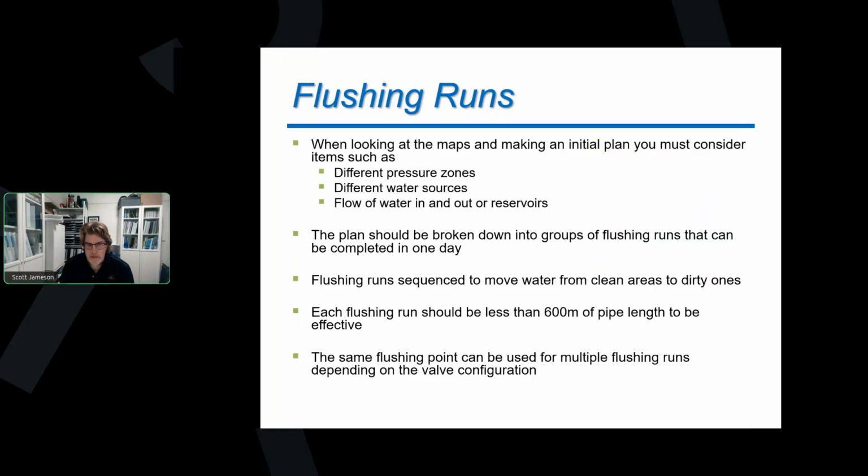The next point is also a pretty important one. We like to try to optimize our flushing runs. We like to do as few flushing runs as possible and achieve the goals that we're trying to achieve. But that doesn't mean that we just go to the very, very far end of our system, close all the valves that it takes to get to that very, very far end, and let it go. We want to try to limit those flushing runs.